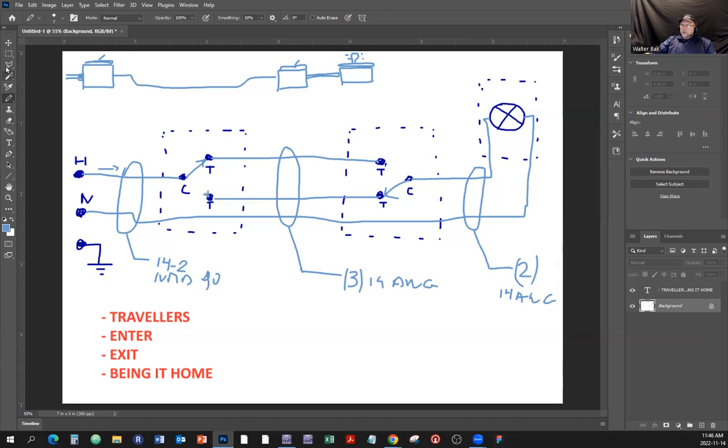One thing that I want you to notice, please pay attention to the neutral. The neutral is electrically uninterrupted, and it goes to the load. So there's no switch going on between those. It just goes straight to the load. And that is correct because neutral is the potential of a ground. So if for some reason you come in contact with the system when the system is off, light bulb is off, you're not going to get shocked. Well, you're not supposed to get shocked.